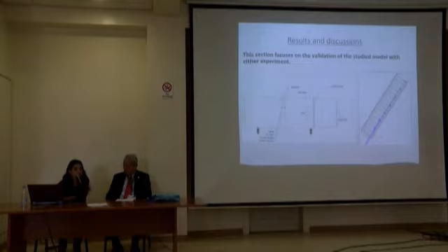The outer cylinder is sheeted by fabric of permeability 0.05 meter per second. 7 thermocouples are mounted in the microclimate air layer between these two cylinders, and each time we rotate the cylinder to measure the angular variation of temperature. The wind speed was 1 meter per second, and the ambient temperature was 25 degrees Celsius.